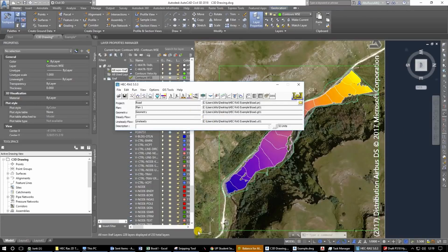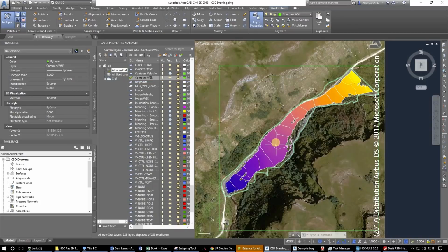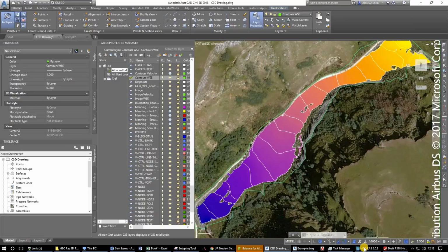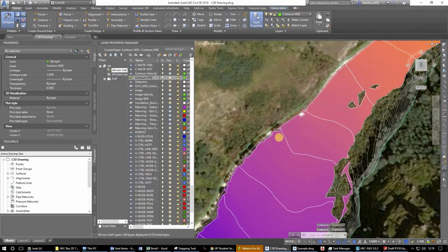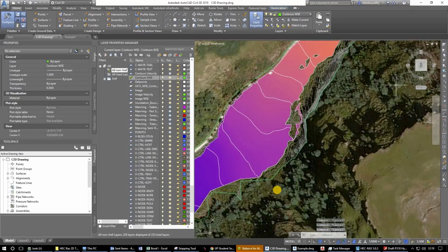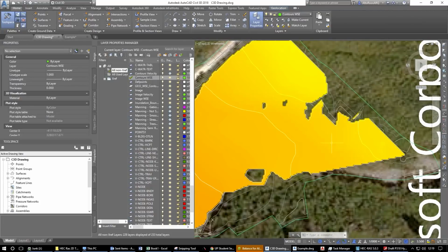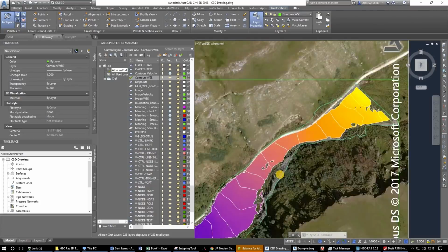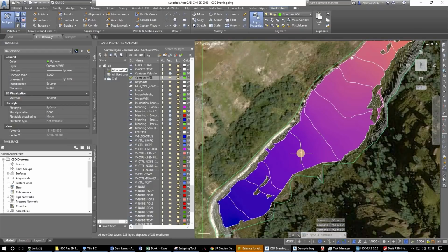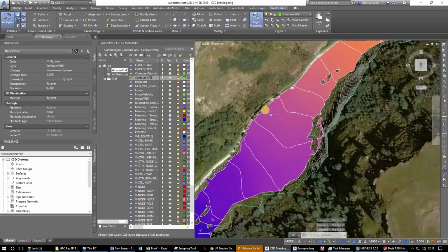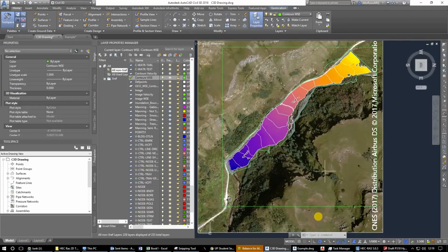sorting out some of the issues, exporting that, going about exporting all of the results that we want from that into a format that can be read either by Civil 3D, or you go over to Quantum GIS, taking that set of data, exporting it with nicely detailed color graded images, and creating contours for those results, and then of course exporting that as shapefiles and GeoTIFF images to be imported into Civil 3D.